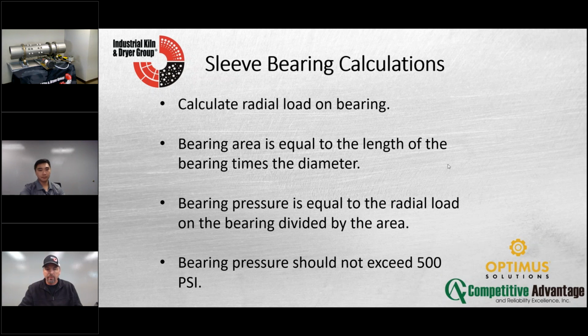We got another question. How much vibration can be considered normal? Is there any recommended equipment to measure vibration? Normal is always an interesting word. The interesting thing about kilns is in kilns, the speed is low, okay? And what I mean by low is it's under 10 hertz. 10 hertz means 10 cycles per second, okay? A lot of the vibration out there that you'll see in terms of the limits are typically for high frequencies, typically 100, 10,000 hertz in that range or higher, okay?